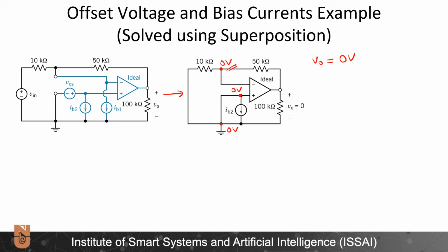Now we are seeing that IB2 is not affecting anything, but this does not mean that in another circuit with a different topology, it would not have had any effects. So it just shows that only for the specific Opamp topology and circuit I have, this time IB2 is not having an effect. You will need to analyze your circuit for different operational amplifier topologies every time, and in those cases, IB2 might have an effect.